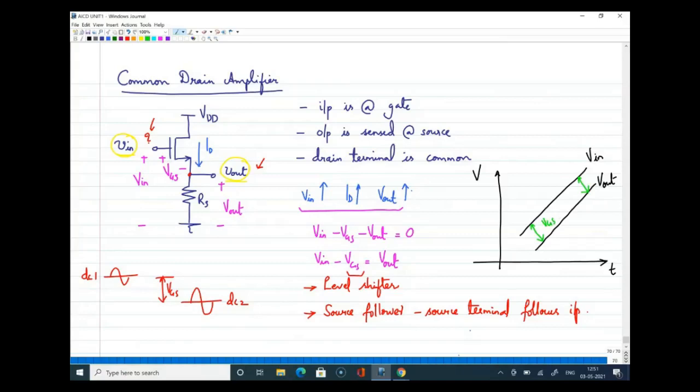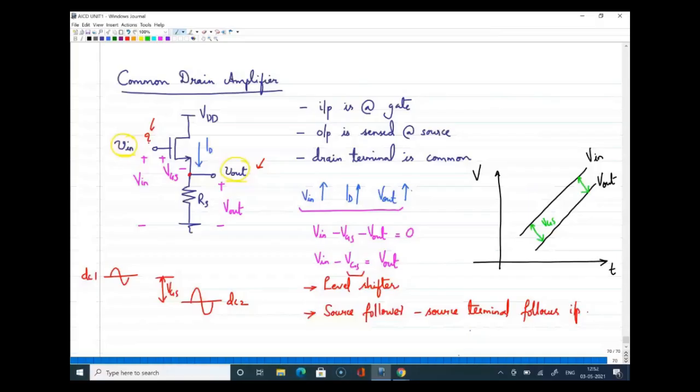So there are many cases, say for example, when we connect from one amplifier to another amplifier, and we observe that both amplifiers have, say, I need to connect a particular signal from the output of a circuit to another block or another circuit, but both have different DC levels, right? You can look at this. One is operating at this DC level, another is operating at another DC level.